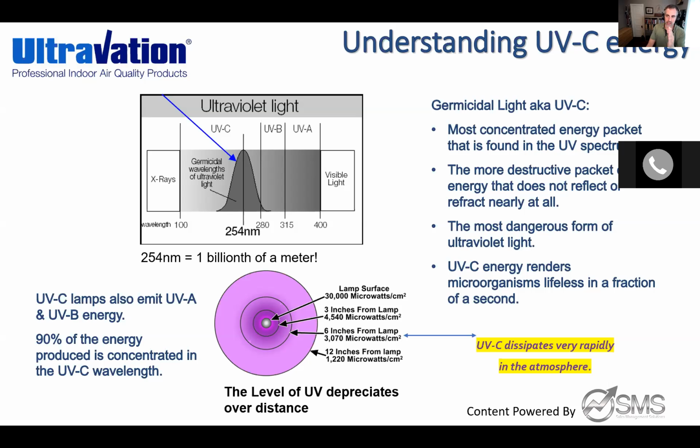As UVC energy emanates outward from the bulb 24/7 throughout the day, that is the intensity of the UVC light coming off. In most recommended applications, for surface area concerns, the closer you are, the more dangerous and deadly it is. That's why, when people are installing these, they should be turned off until installed. Contractors should be using protective goggles. You can burn your skin and your eyes with UVC wavelength. That's how dangerous it is. We like to remind people from a training perspective, because people need to be safer with this. I've actually met people who have gotten injured from this.